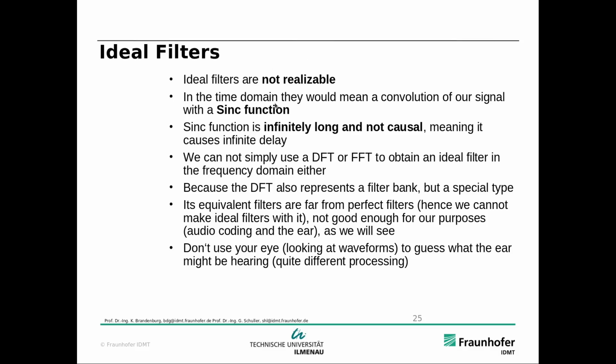Yeah, so ideal filters in the time domain would have a sinc function as impulse response. That means filtering with an ideal filter would be a convolution with a sinc function. But the sinc function is infinitely long, going from minus infinity to plus infinity, which also means it's not causal, which means it would cause an infinite delay. And that means it's not working.